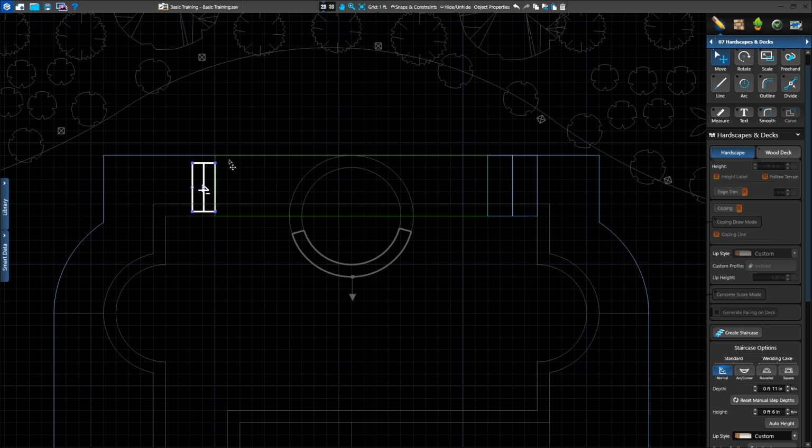The top points, or the points on the shape where the staircase was attached, can be moved to change the overall shape of the staircase. Using the Move tool on the bottom points lets you change where the staircase ends and can give the staircase a unique shape. We can also pull the point in the middle of the stair to give it a unique depth. We'll adjust the top points to match the 5-foot side of the hardscape.